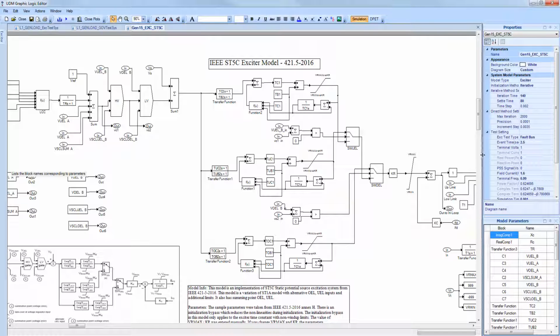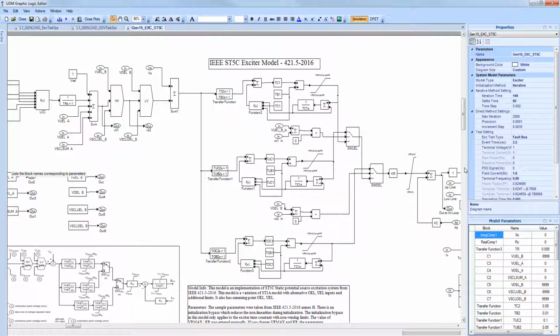For the excitation systems and for governor systems in ETAP 16, we redefined the way the test routine is executed. First, we added a new simulation capability which is called none, and it stands for an actual no-flow event, or an event where we expect the excitation system or governor system to reach steady state conditions. This test was designed to simply observe if our exciter can reach steady state conditions and remain in those conditions throughout the duration of the simulation.